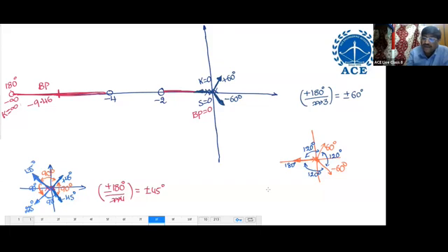Draw the diagram. What is the diagram? As k increases, these two poles initially move right, but one pole comes to the left. It will go on, moving left. It occupies the zero when k equals infinity. One pole gone, one zero completed. How many poles remain? 2 poles. How many zeros are there? 2 zeros are there.